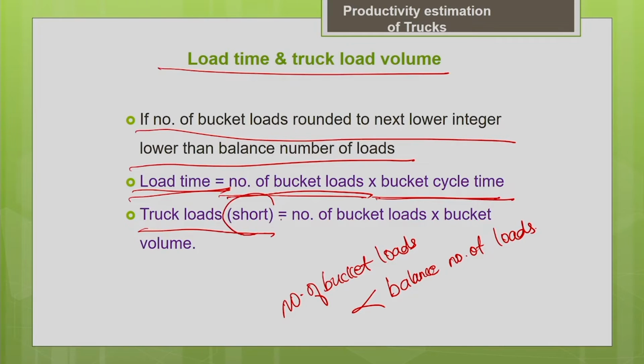The truck load will be short. Sometimes we prefer a short load, say for example, when you are climbing steeper grades, we do not prefer loading the truck to its fullest capacity, we prefer short loads. So, in this case, since the number of bucket loads is lesser than the balanced number of bucket loads, it is called a short load.